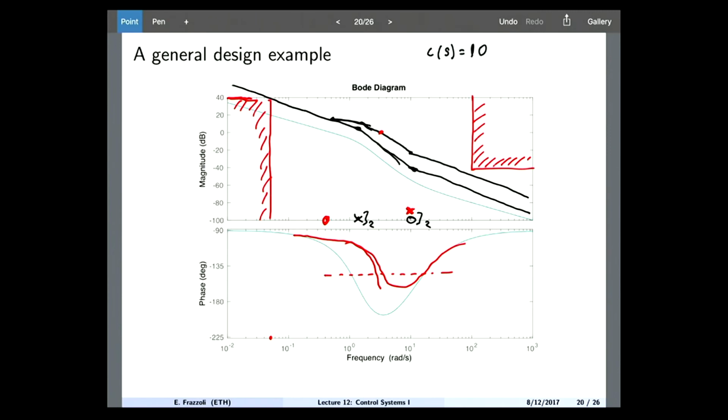What happens to the high frequency noise sensitivity? Still, if I've done my Bode plot correctly, I'm still clearing this obstacle, given this new lead compensator. So with this very quick, back of the envelope, or back of the iPad kind of design, essentially what we are saying is that this is S over 0.4 plus 1, over S over 5 plus 1.